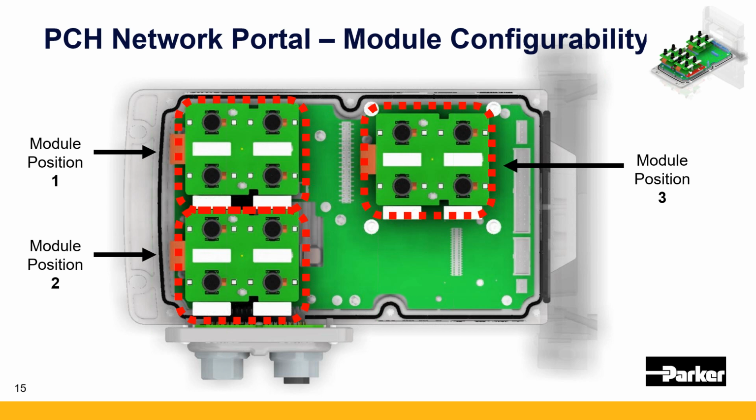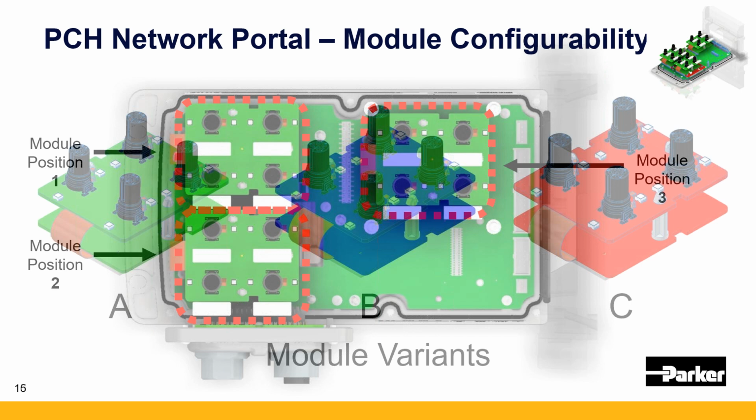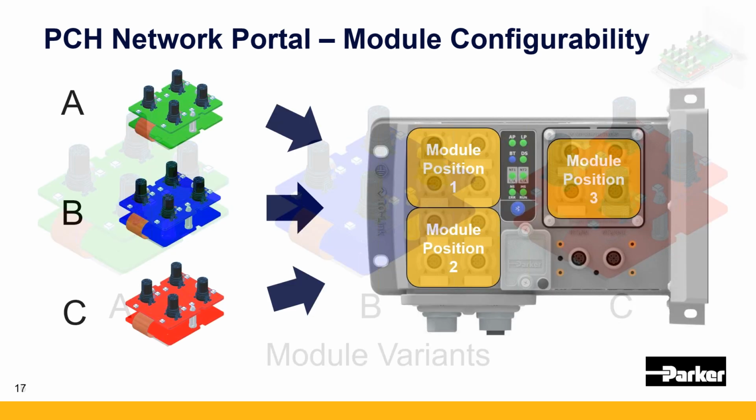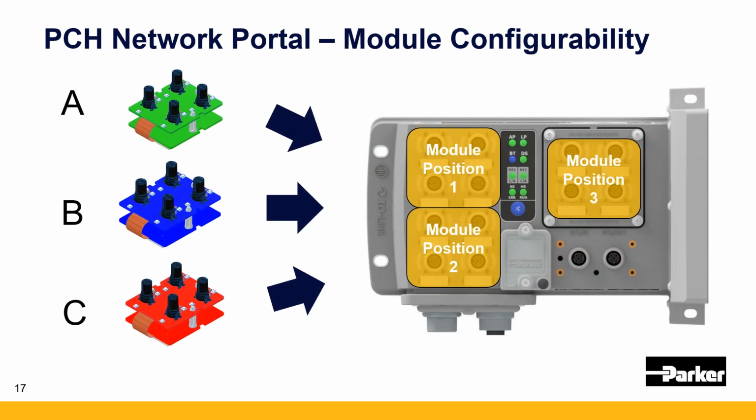This housing is an IP65 weld splatter resistant housing. We do this kind of material now on all of our network nodes because we want to survive in an environment with a lot of weld noise. There's electric zoning and, with the ISO valves, pneumatic zoning. This is safe power capable, up to 32 coils, so you can have 32 ISO valves. And we're going to talk a little bit about an exciting feature, secure and lockable Bluetooth.